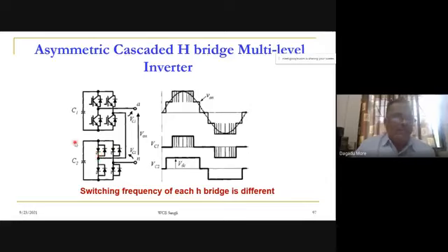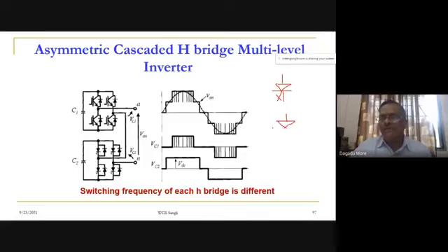At the gate we have a cross. What is the GTO symbol used? I will just show it here. GTO is the gate turn off thyristor. This is our thyristor symbol, and if you make a cross on the gate terminal, then you can call that device a GTO. So this is the GTO symbol, and the lower one I am drawing is the thyristor symbol. This will be one way to represent the GTO.